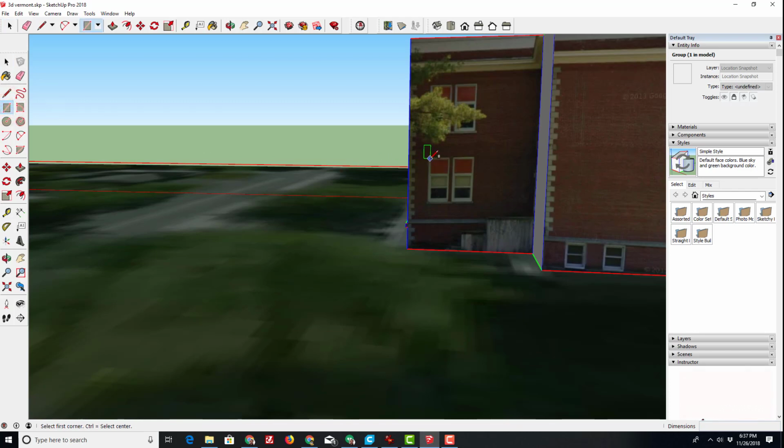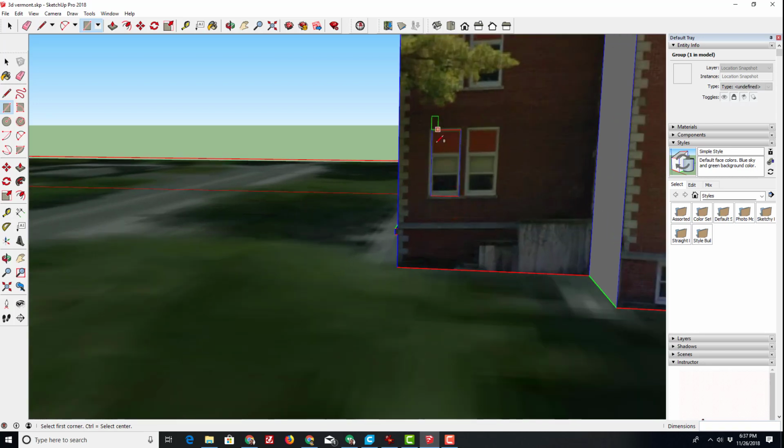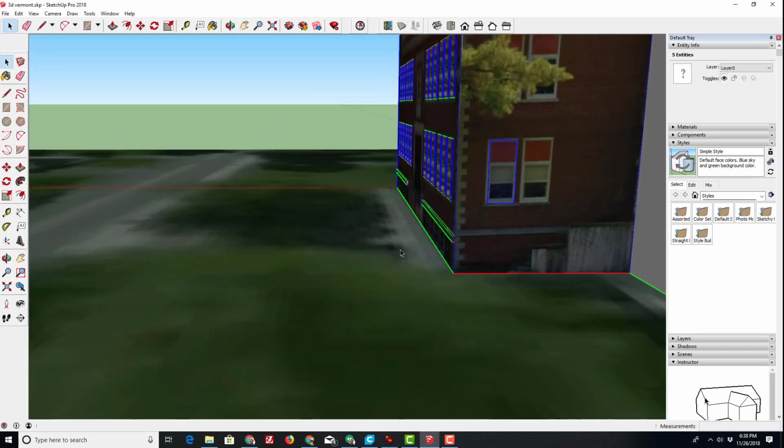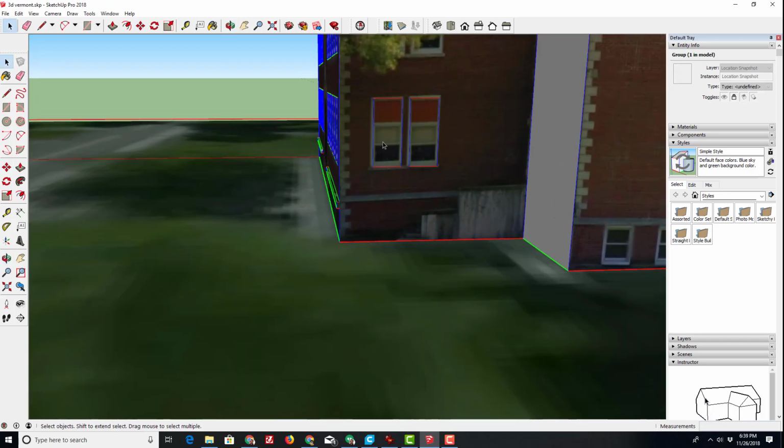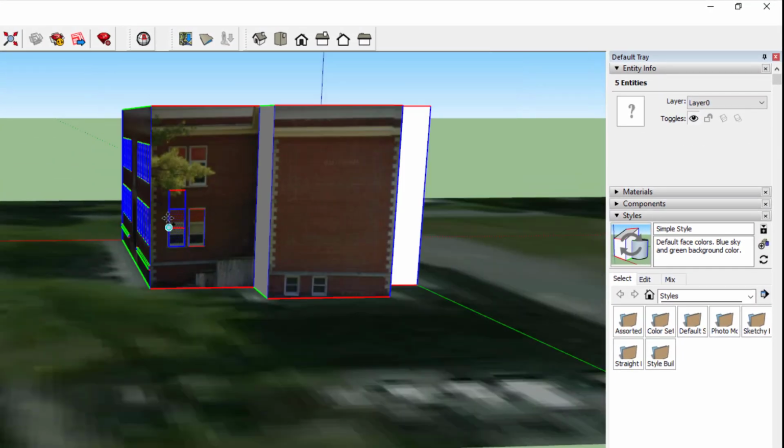Remember, it is the rectangle tool. And then when you click and set it down, notice those lines match. We can select it by triple clicking it, and then do the M for move. Switch control or tap control so you're in copy mode, and drop it in place. I'm going to just use that same triple click, move, tap copy. And let's move that one straight up where it goes on the wall. Notice it gives us the nice blue line to prove that it's in place.